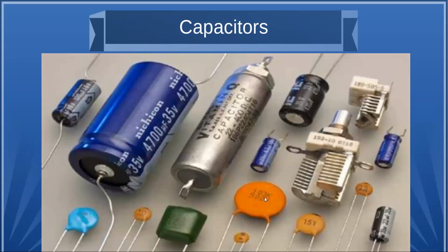These are ceramic capacitors, which are 2 metal plates separated by a piece of ceramic. These are what we call air variables, which you use for tuning, basically, having an adjustable capacitor. And it's still 2 plates separated by air. One of them moves, so the plates can mesh together, and how much they overlap determines the amount of capacitance.